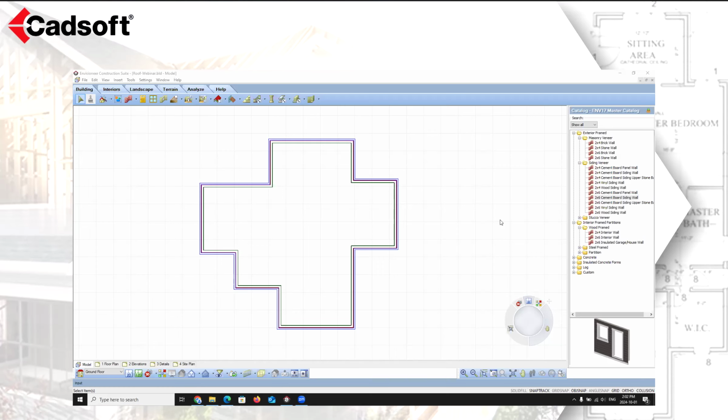Once you have inserted a roof, you can then edit each of its support segments to create virtually any configuration. For example, you can control the slope or the plate height of individual segments, or if you've inserted a hip roof, you can convert it to a gable end.